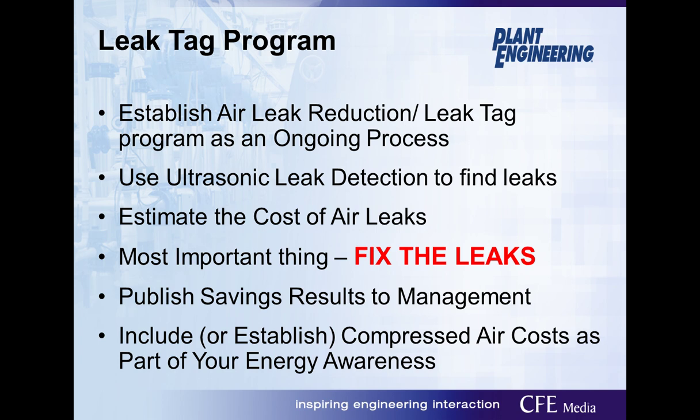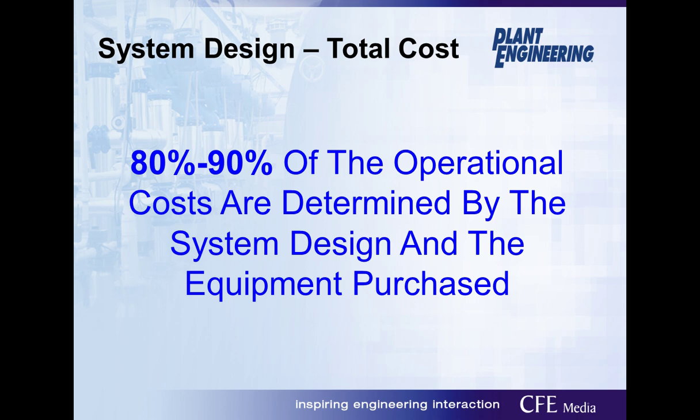And I am a big believer in, if you can do a find-and-fix program, which basically says fix as many of them as you go when you're doing your leak tag, do it. Publish the savings results. And again, you need to include this as part of your energy awareness, and we'll talk about that coming up with a case study example I have.